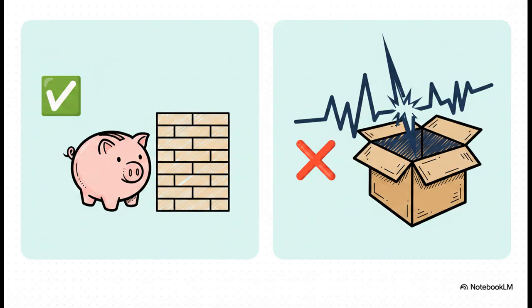Like any good workhorse, it's got distinct strengths and weaknesses. On the plus side, you're looking at a much lower initial investment. It's incredibly durable and boasts a lifespan of 15 to over 30 years, which is just fantastic. But it has some critical flaws. It takes up a massive physical footprint, sometimes we're talking the size of a large refrigerator, and it is terrible at handling changing loads. Plus, it carries a high risk of system resonance and can actually cause a leading power factor when you're operating at light loads.